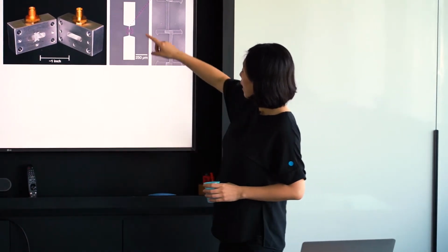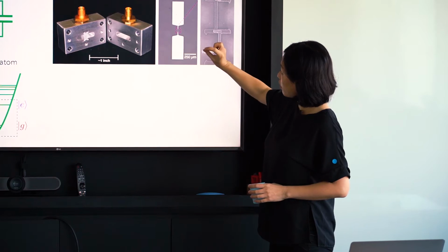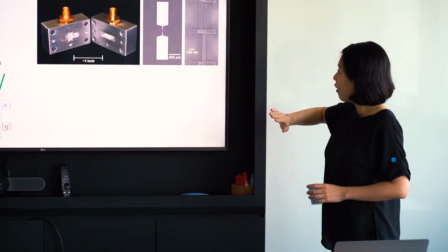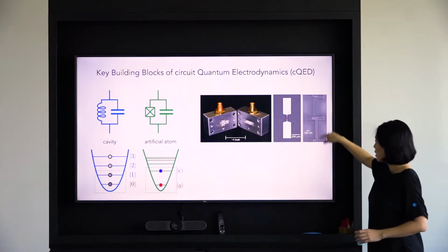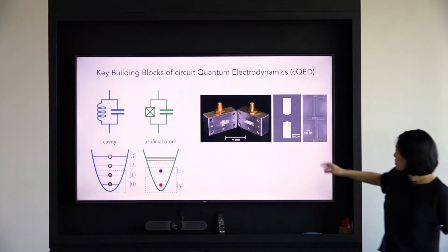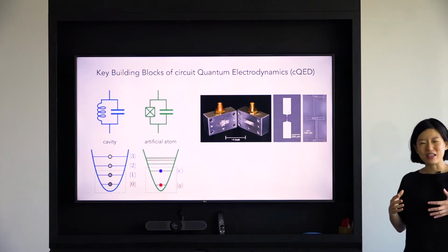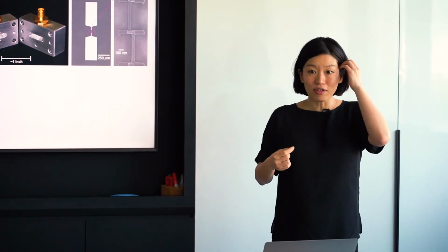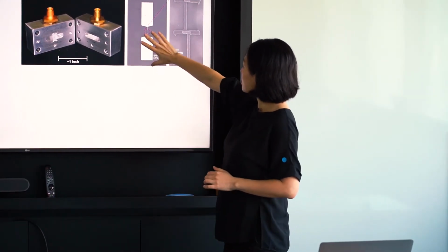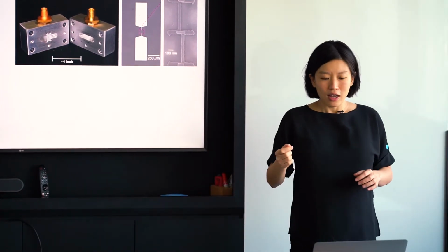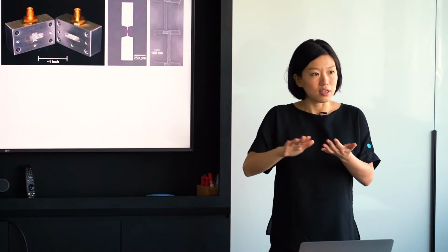Okay, and physically they can look something like this, where we have some very thin metal film patterned on the substrate, and inside, the little Josephson junction element just looks like this. You can see the scale bars here, they're not really tiny as you would imagine, like a single electron or a single photon, but rather they're quite big and you can see them in a microscope. Okay, and the beauty of this is that you can see these features and they remind us of the good old classical circuits that we print on the circuit board, right?